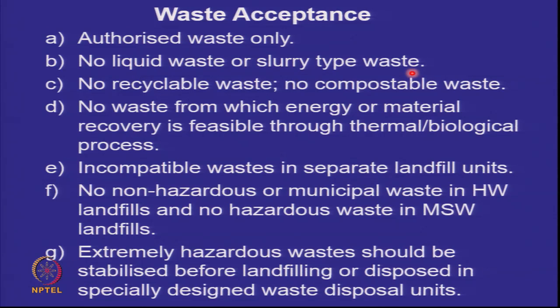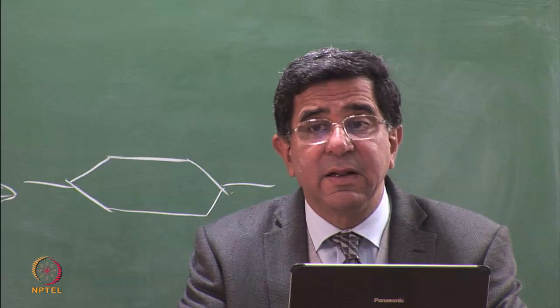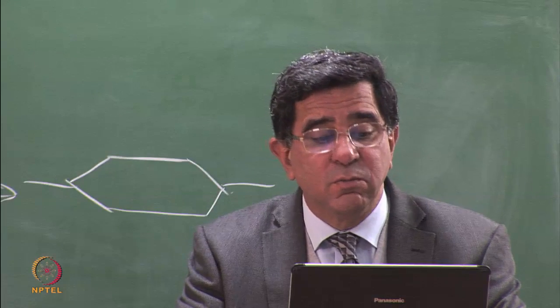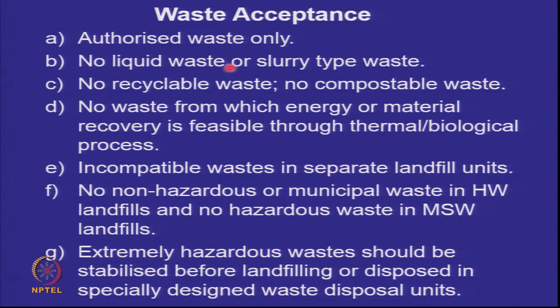If you have a slurry type waste which is a lot of water, you have to dewater that and bring it in the form where it will not move. So authorized waste only, no liquid or slurry type waste can come in landfills. Landfills are not designed like ponds.